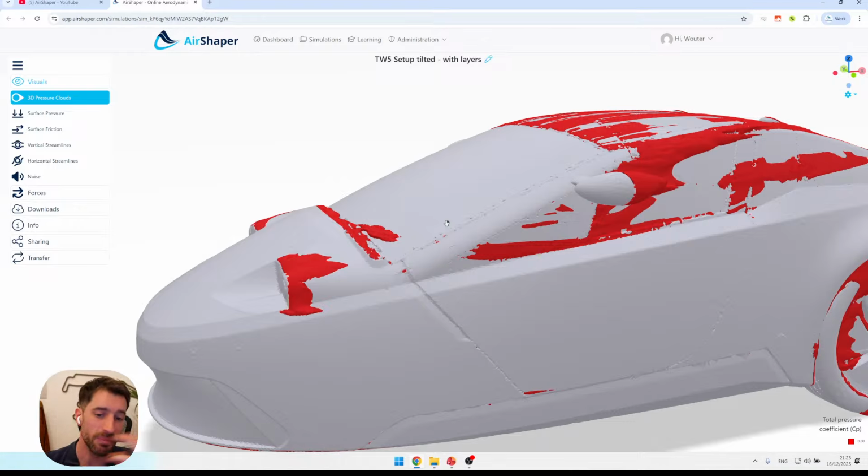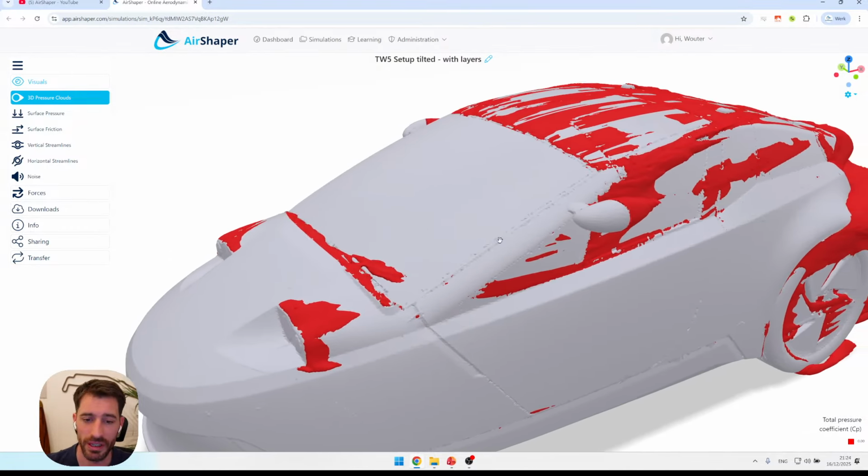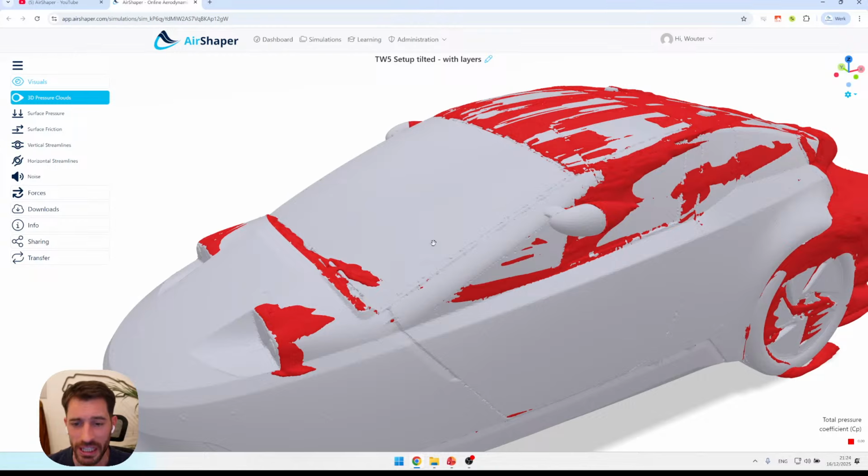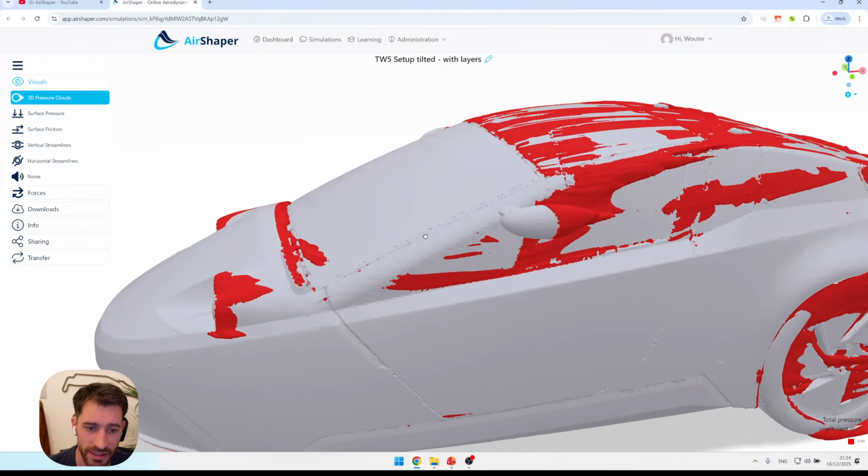If you increase the mesh resolution and you see that your drag coefficient doesn't change much, then you can usually conclude, okay, we can make do with this resolution without spending all of our time and effort on the highest resolution. So the bulk of the work was done with our regular simulation of 10 million cells.